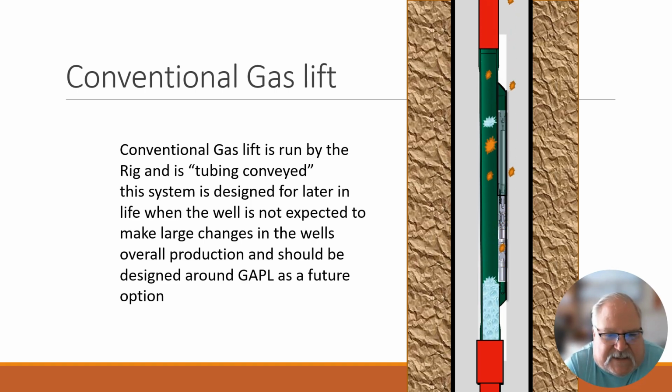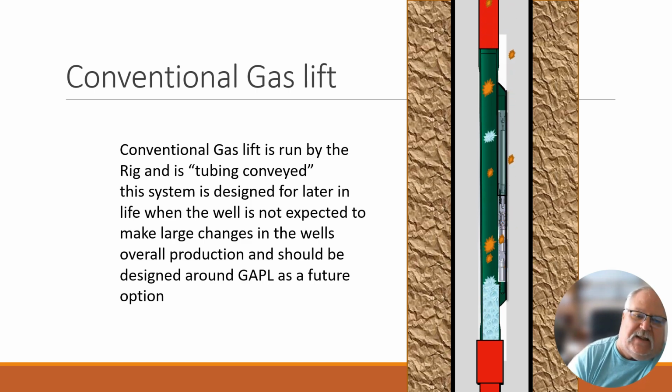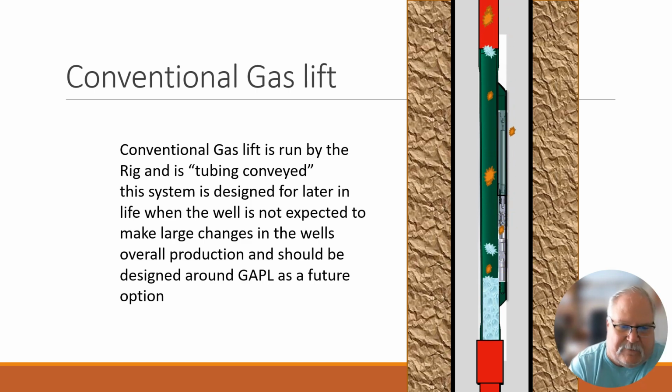And then we have this: gas is injected, goes through the valve, injects through a small orifice into the mandrel, which then gasifies the liquid column. If you're in true gas lift mode, you're just basically gasifying that column, foaming it up, allowing it to get to surface where the well's own pressure can kind of push it out and fill that bucket.